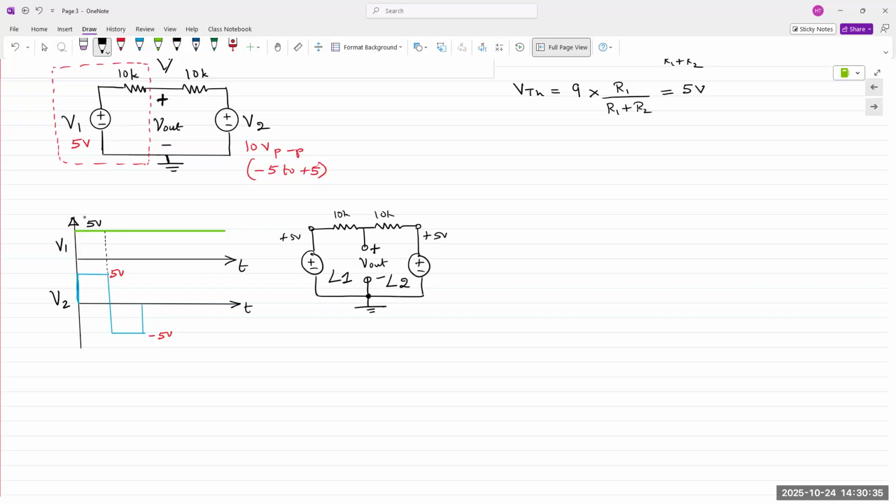If the voltage at both ends of those resistors is zero, what is the current? Also zero, which means the voltage drop across these resistors is 0 volts. If the voltage drop across these is 0, you apply KVL, what do you obtain? You can apply KVL to loop 1. What do you all think?